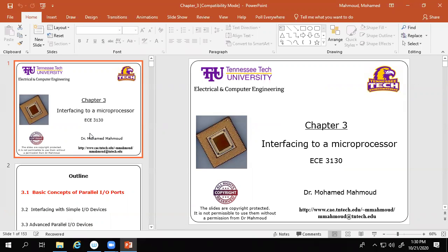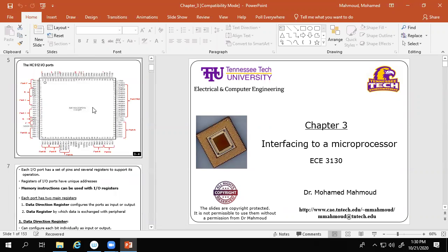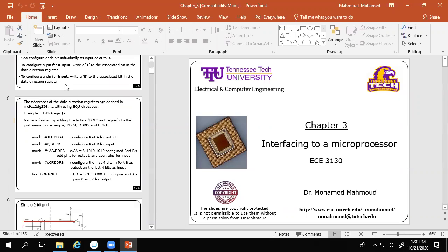In this chapter, I'm explaining how you can program input-output devices here on the board, using both C and assembly. I already explained how you can program the LEDs. We have 8 LEDs, as I explained. I told you they are connected to port B, and you also have to use PJ, because PJ1 is the enable as well.